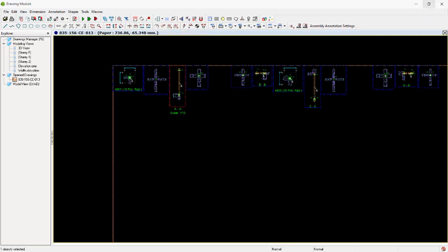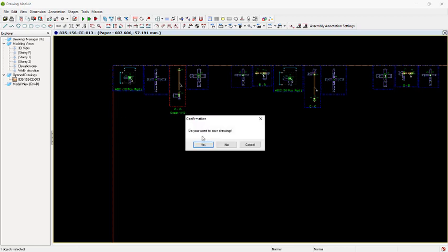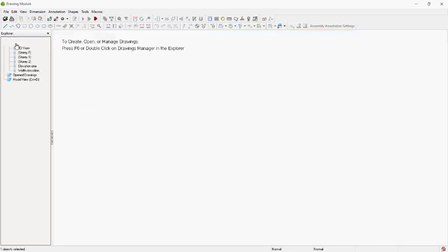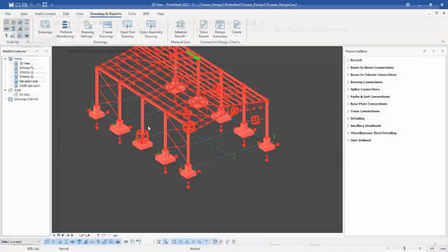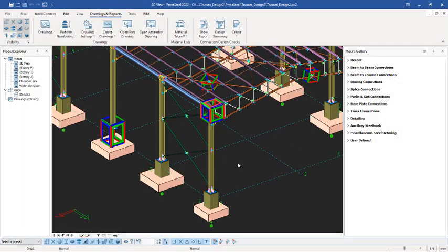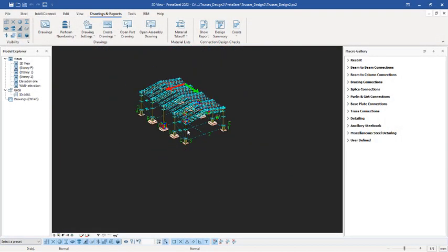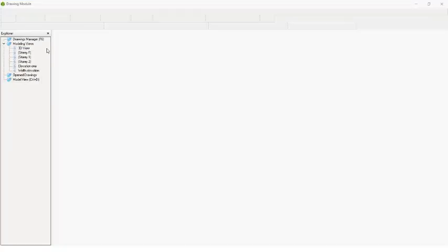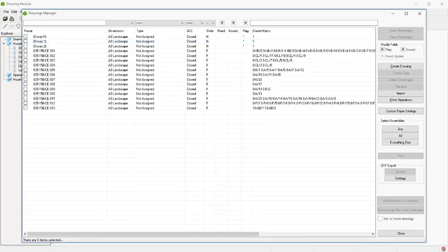What we need to do now is close the drawing modules. So you click yes to come out there. At this point, we double click on the 3D right there. We need to get out of this drawings module, so you click on this close option right there. So we are here now. What we need to do is export those drawings we created. Double click here to AutoCAD.